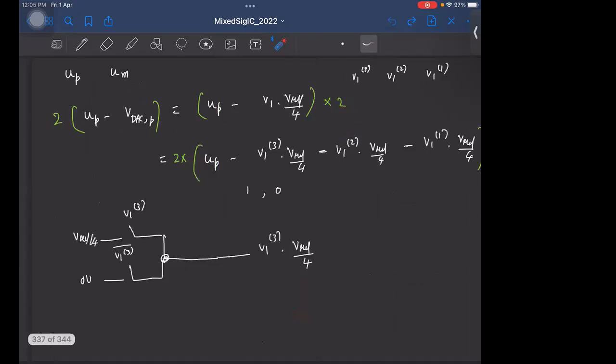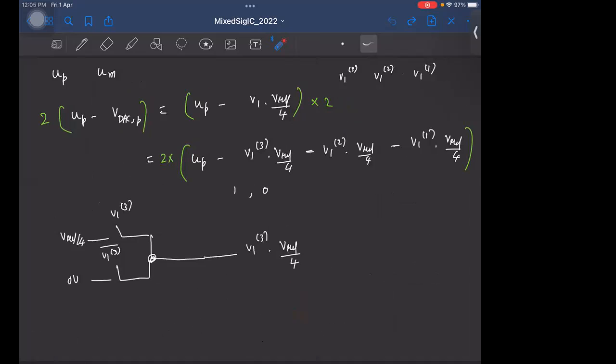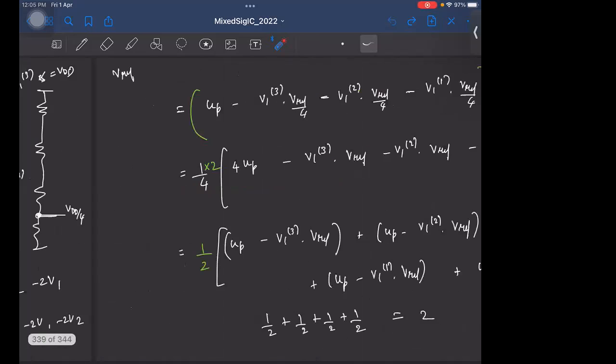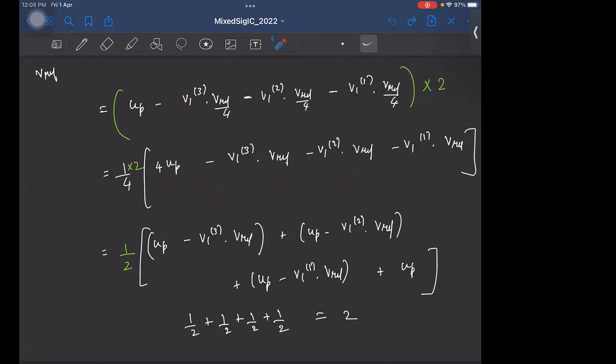Right. So essentially it turns out that this input minus the DAC output is of this form, right? And for the 2-bit ADC, we wanted a gain of 2. So this is what we want to have at the amplifier output. And this portion in turn was rewritten slightly like this, right? Where I multiplied and divided by 4, and I rewrote the output you want in this format. So we now have 4 such inputs to be amplified, and each needs to have a scaling factor of half.